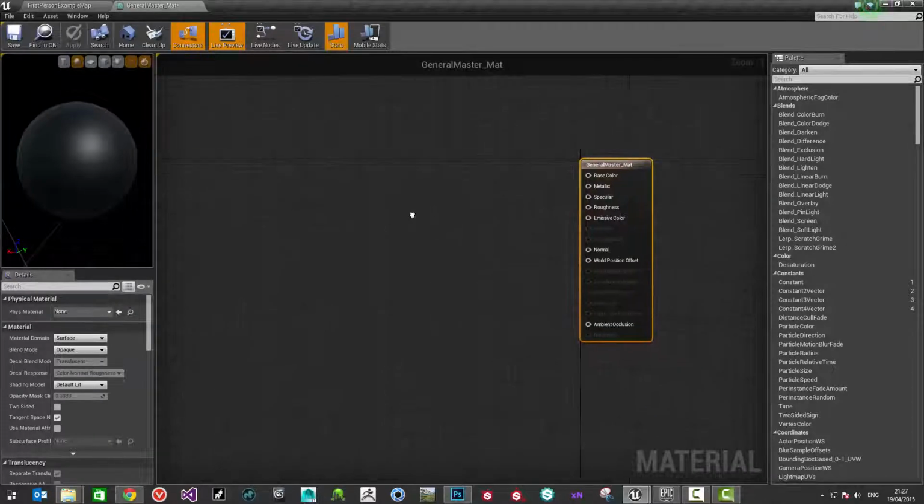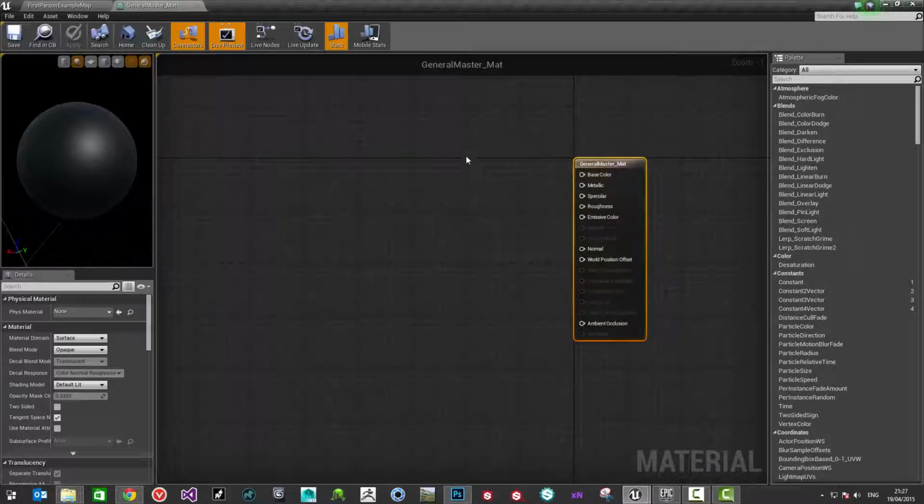The textures which are going to be used for materials if we were working on a project in a scene won't actually be dealt with directly inside the master material. We'll add those textures in our material instances once we expose them. What we're going to need is some placeholder textures just to plug in here as inputs.